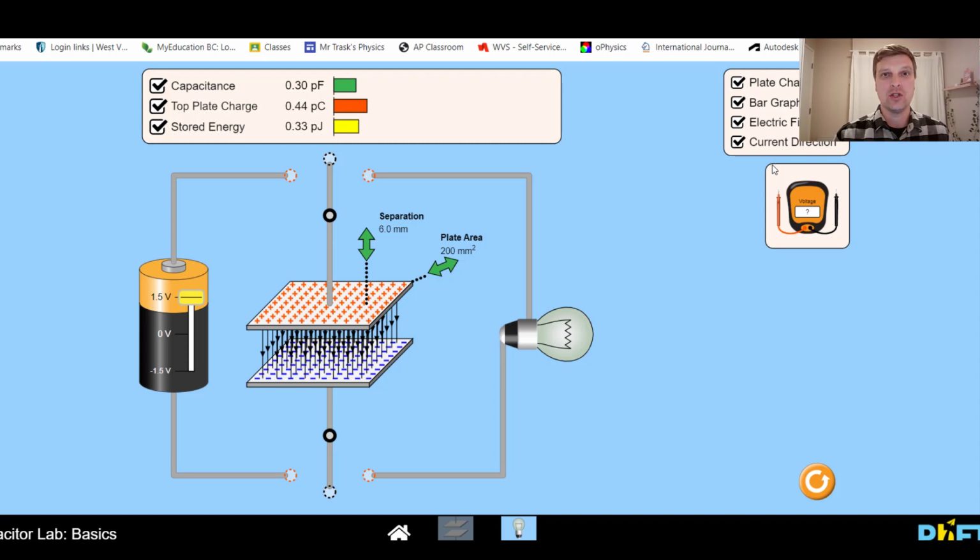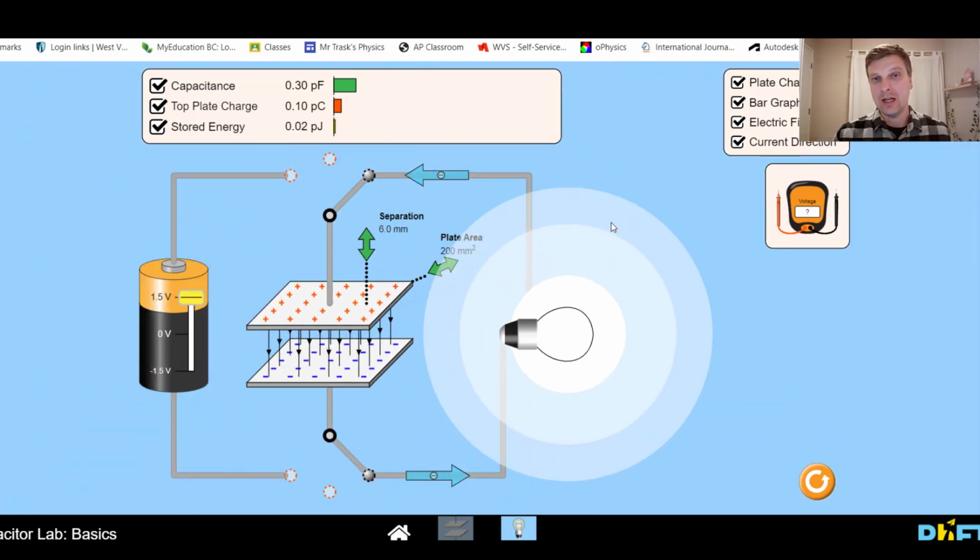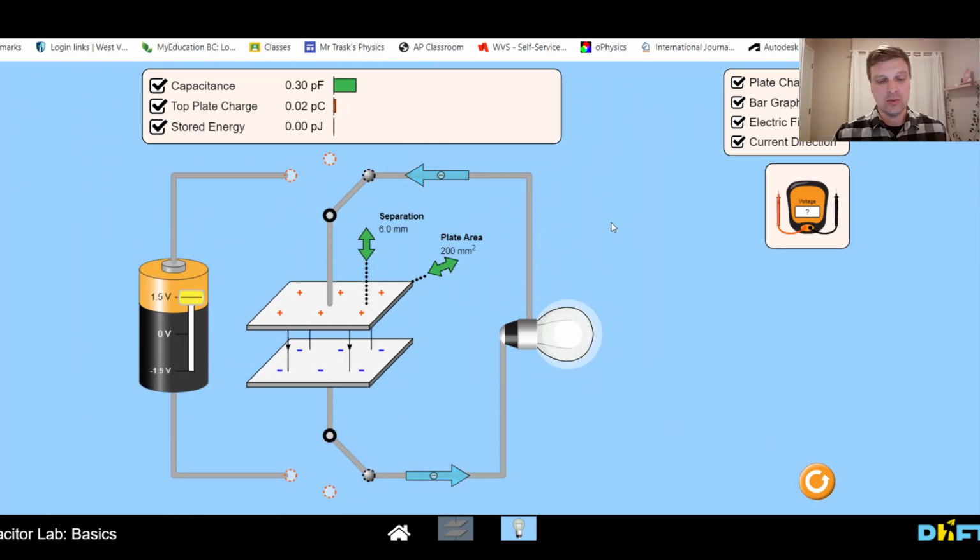And if we're storing a bunch of charge, then we're also storing a potential difference, which means we're storing energy. I could, for example, take this capacitor and connect it to another circuit, and that would then release that charge, release that energy, electricity would flow back the other way, and I would get it in a way that's different from a battery. Whereas batteries tend to have internal resistance built right into them, this capacitor doesn't. And so I can deliver a pretty high current in a really short amount of time. That's one of the reasons capacitors are useful.